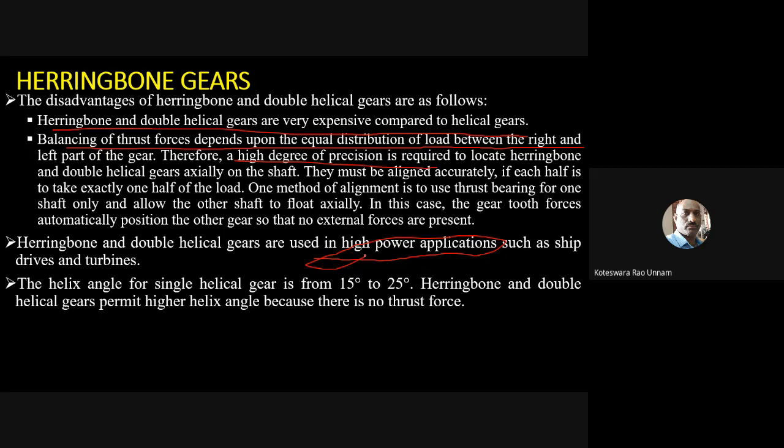If it goes on increasing, we know that sin alpha increases as alpha increases. Even the tan value also increases. If you look at the expression for the axial thrust load, PA, it is a function of your helix angle. If the helix angle increases, your thrust force will also increase. So that's why it should always be kept less than 25 degrees.